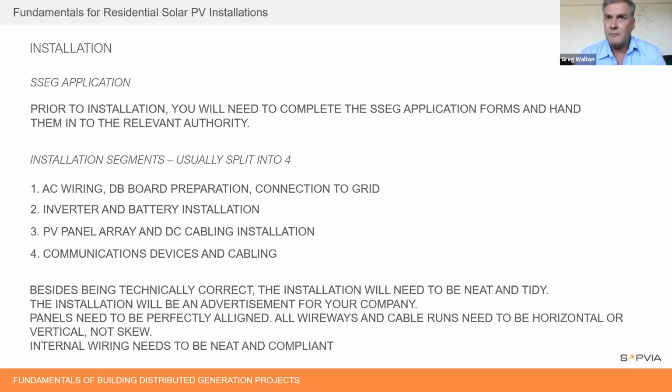And the cabling, the DC cabling is critical as well. We use sometimes Bosal, sometimes we use a metal trunk that we develop, sometimes we use other methods, but everything's got to be done correctly. And the fourth group that comes along and does the communications, which is highly important. I mean, if that 0.25 millimeter copper cable isn't sitting perfectly in that jack, then nothing works. So comms is very, very, very important.